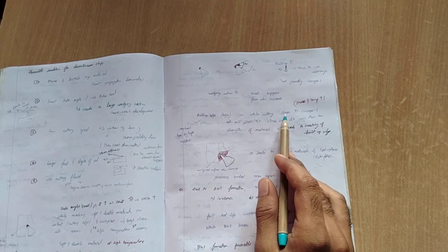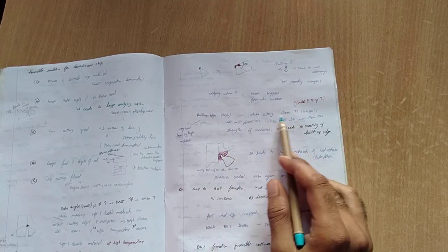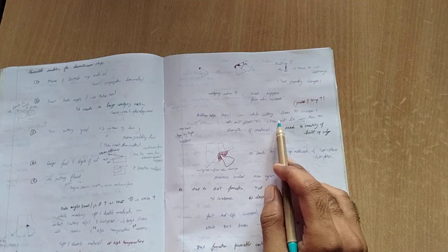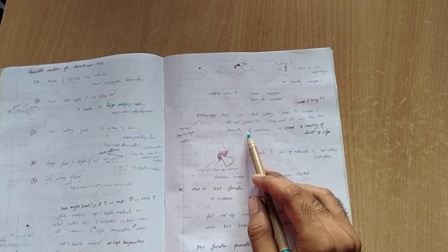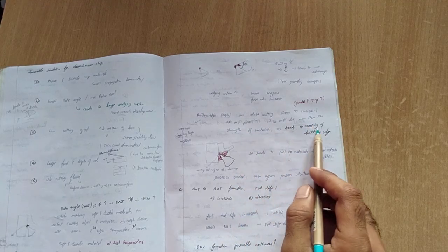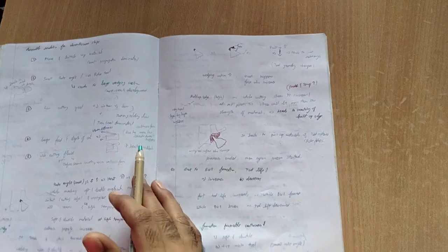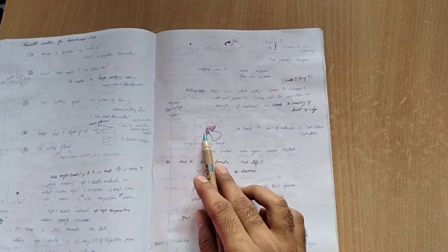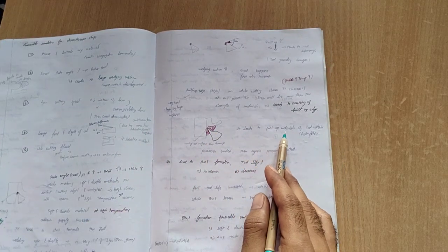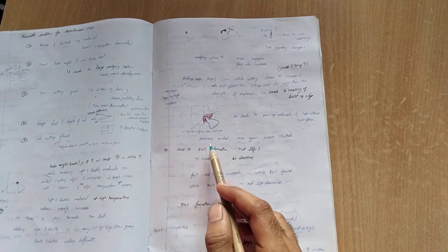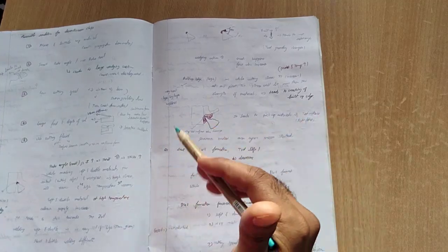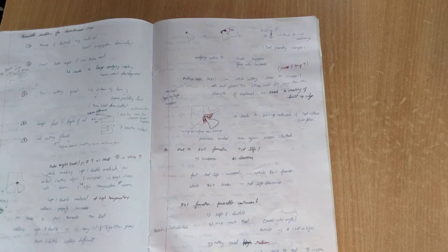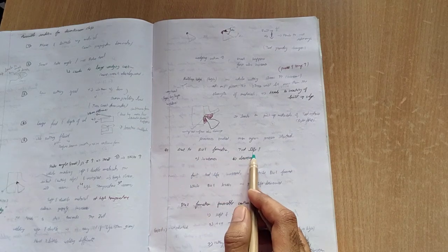While cutting stresses increase, at one point the stress becomes more than the strength of the material, leading to cracking of the built-up edge. It increases and leads to pickup of tool material. The process ends and then starts again. So due to built-up edge formation, tool life decreases.